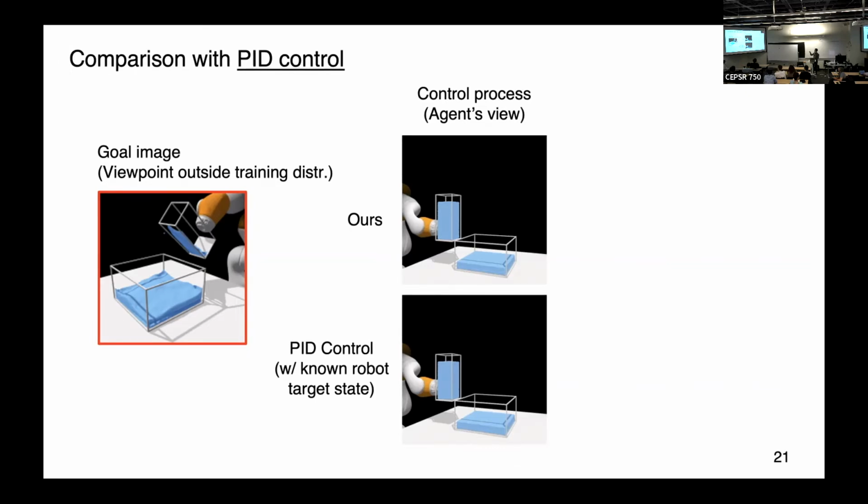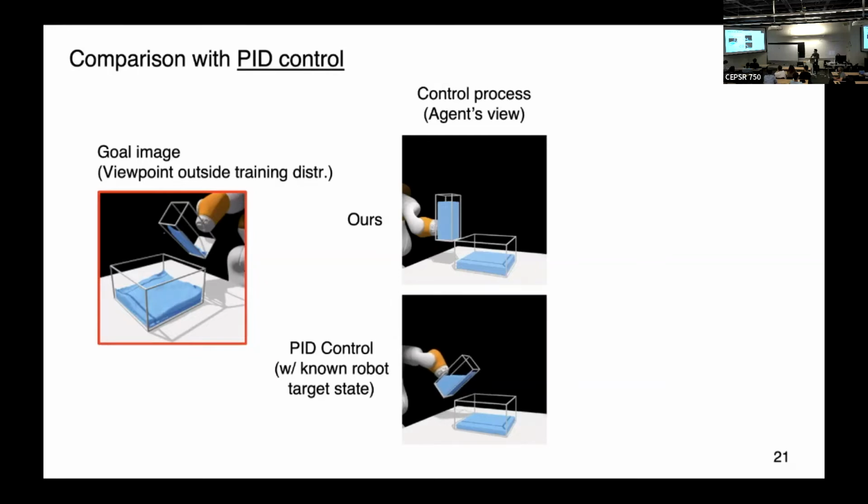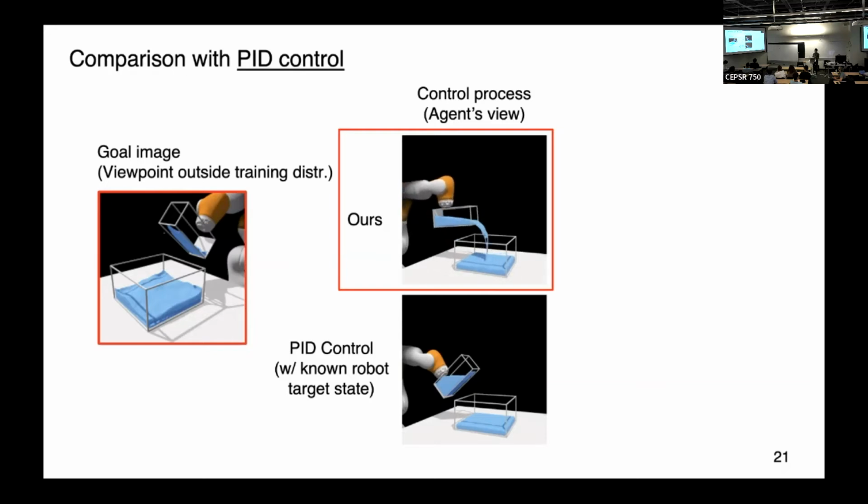On the left is our target we aim to achieve. There's a little bit of fluid still remaining in the container. We first show what happens if we use a PID controller, where we only want to match the pose of the container. It won't be able to pour any fluid out. By using the dynamics learned by our dynamics model, we'll be able to use MPC to reasonably accurately pour a certain amount of fluid out and also tilt the container back to match the targets.